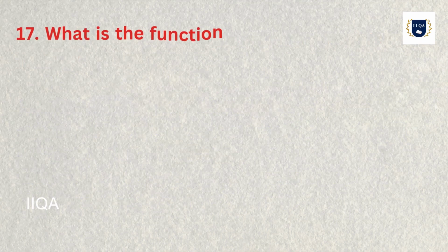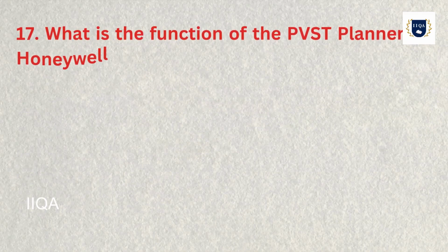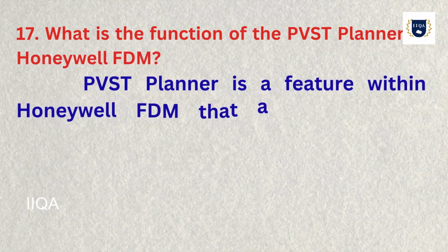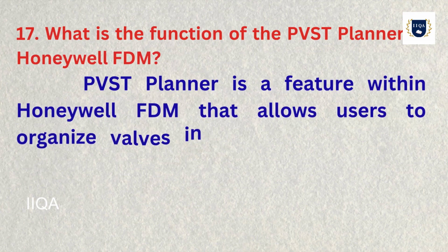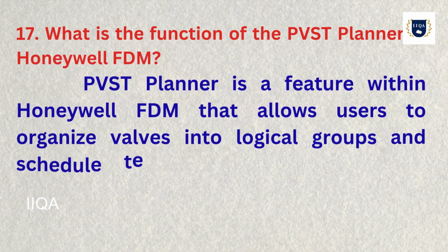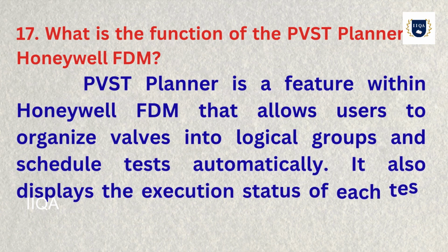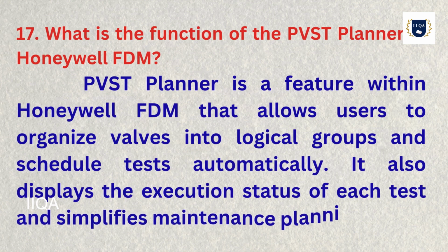17. What is the function of the PVST Planner in Honeywell FDM? PVST Planner is a feature within Honeywell FDM that allows users to organize valves into logical groups and schedule tests automatically. It also displays the execution status of each test and simplifies maintenance planning.